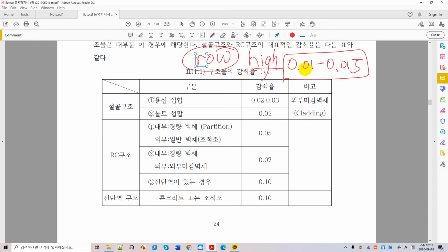If you make a mistake in putting the damping ratio in real large scale when you work in the future in the company, then you're making very big mistakes, because your building stops very fast and your building deflection is very small. You remember what's the limit of the building deformation that you use when you design a high-rise building? I said, if you remember, delta equals L over 400 through L over 600, right?